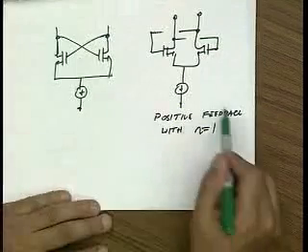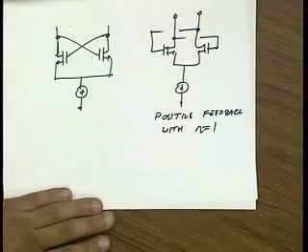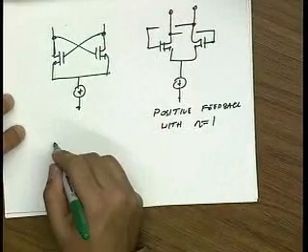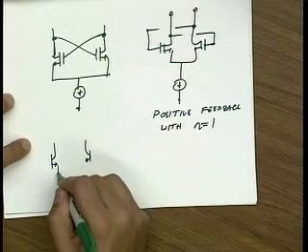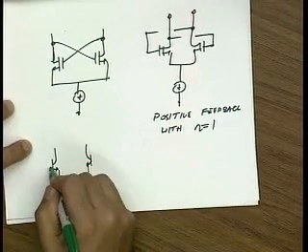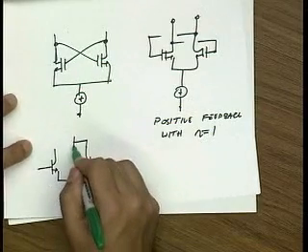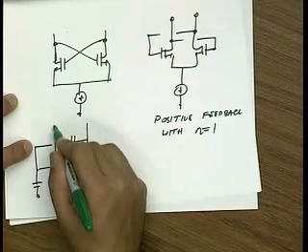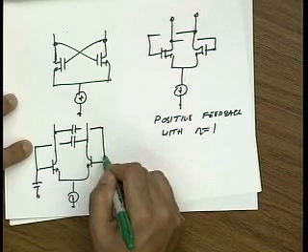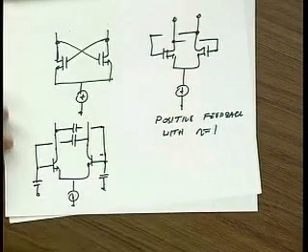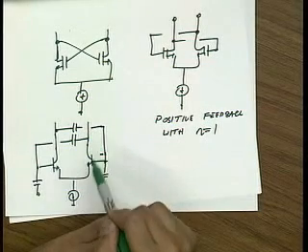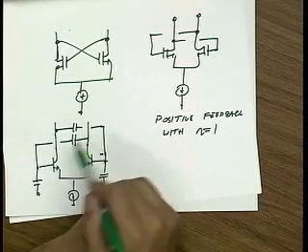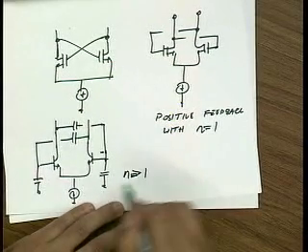And so in fact, if you want to have another value of n, what can you do here? Just use a cap divider. So in fact, what's very common for a bipolar version of a cross-coupled pair, what you see is people doing something like this. So again, this is the same idea. I take the output, bring it back into the input, but now I take a fraction of the output. So this is positive feedback with n basically bigger than 1.